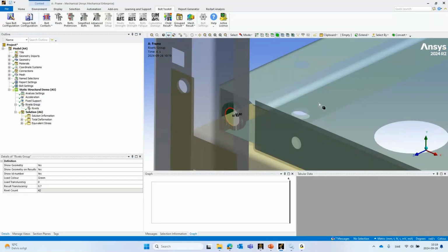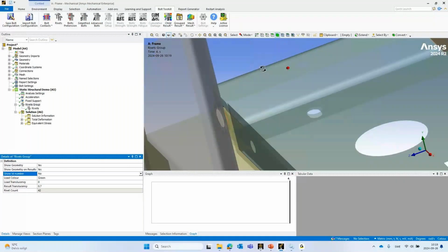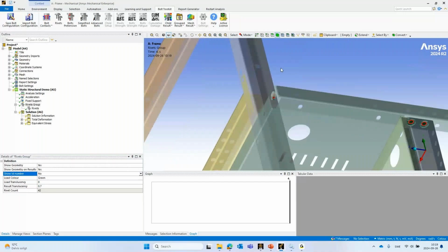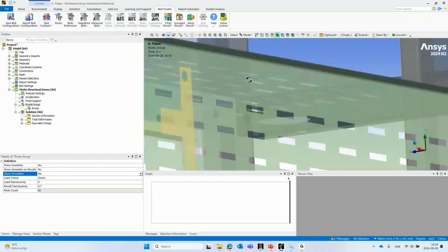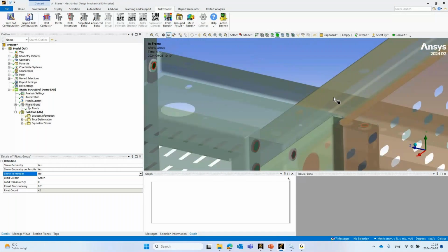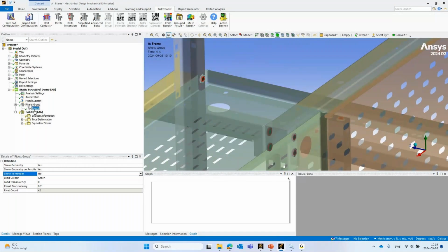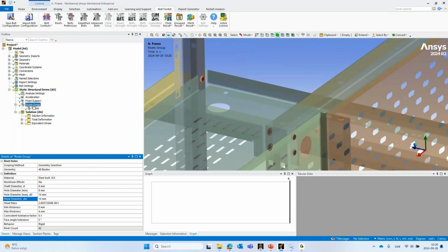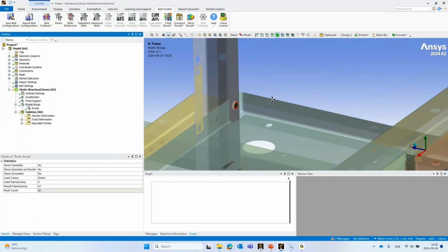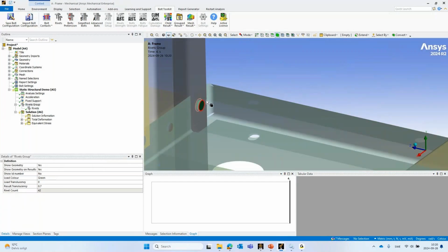For instance, I can toggle the ID number. So directly a visualization of the shaft diameter, the head diameter. If I don't want to use a head diameter, I can directly just fill in the same diameter as the maximum hole diameter. That means the connection is only using the edge of the hole.